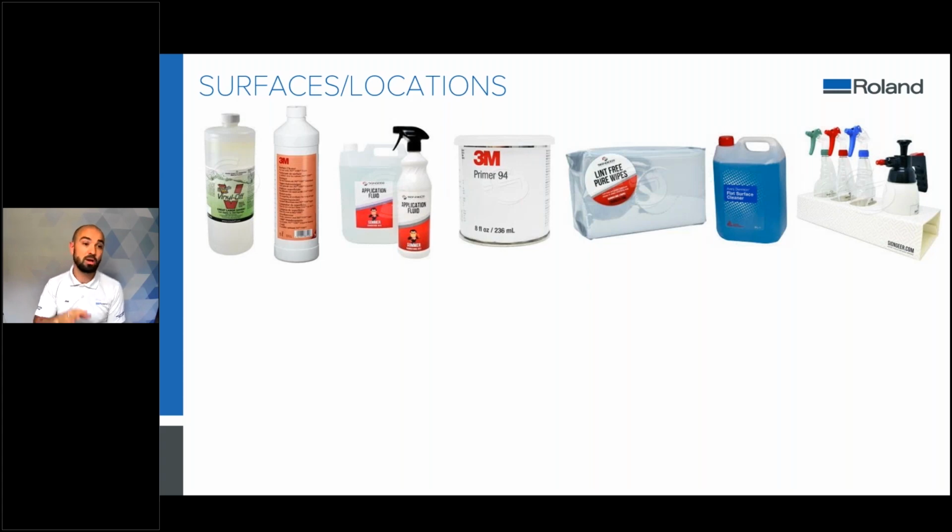So there are solutions for cleaning surfaces as well. Cleaning is a huge part of applying graphics. Walls will be dirty, no doubt, especially if they're in high traffic areas. So you will need to clean the walls down as much as possible. If they have lots of imperfections in the wall, you may want to give them a light sand as well. Again, if you're going to light sand the wall, then you're going to need to get the sanding dust off afterwards with a damp cloth and then wait for that to dry before applying your graphics.